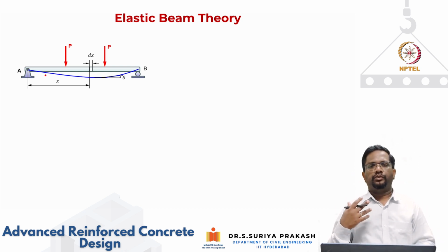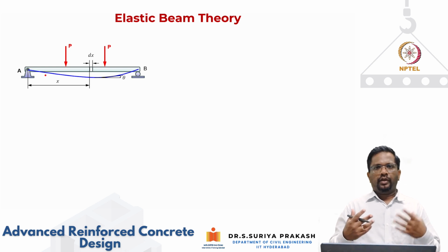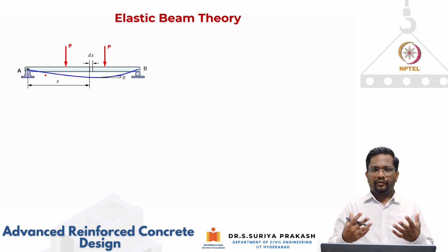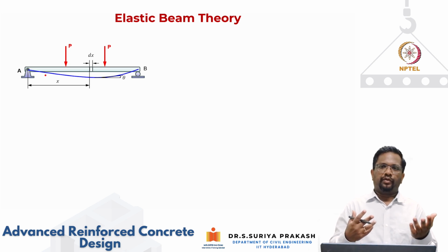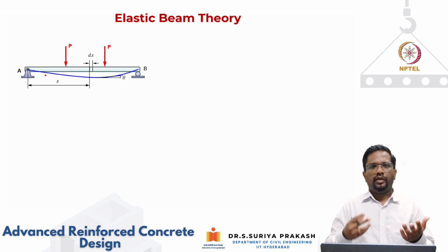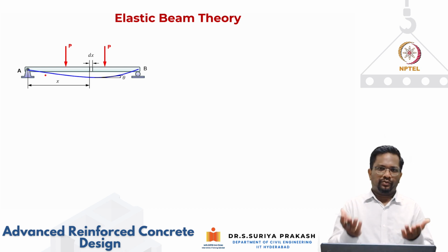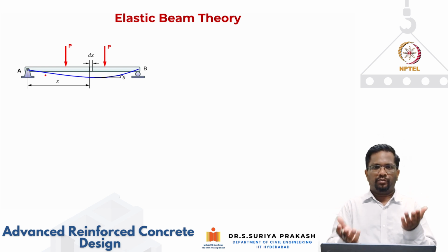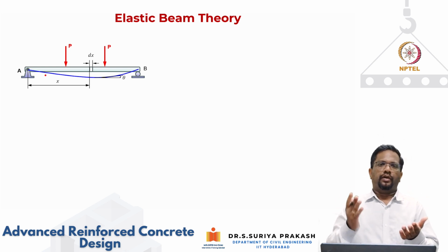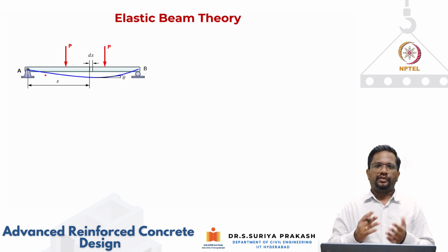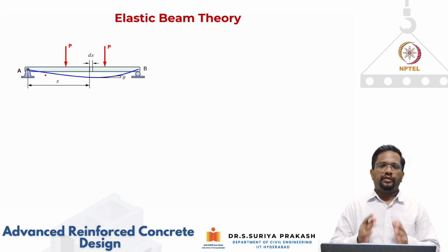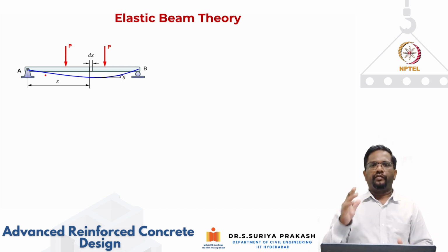Why do we need to do moment curvature analysis? It gives us an idea, if I want to compare the performance of a particular beam with different amounts of steel, or if I want to change the strength of the concrete. I want to compare between two things: how much strength is increasing, and how much rotation capacity that particular section has. For that, in a normalized way, if you do moment curvature analysis, we can get a very good idea how